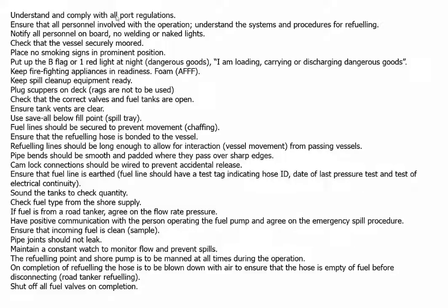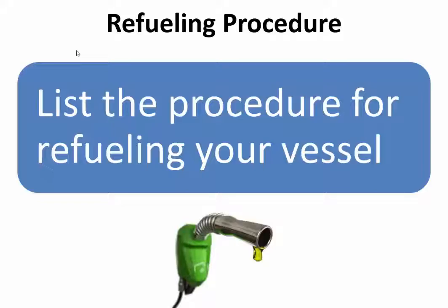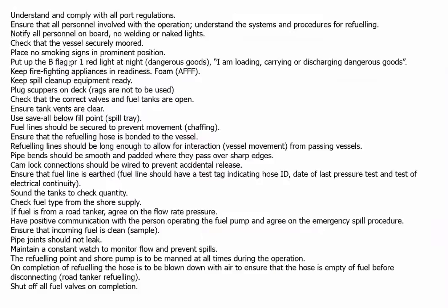So we've got: comply with port regulations, ensure personnel involved understand the system, notify all personnel on board, no welding or naked lights, check the vessel is securely moored, no smoking signs, B flag, the Bravo flag, red flag or one red light at night.